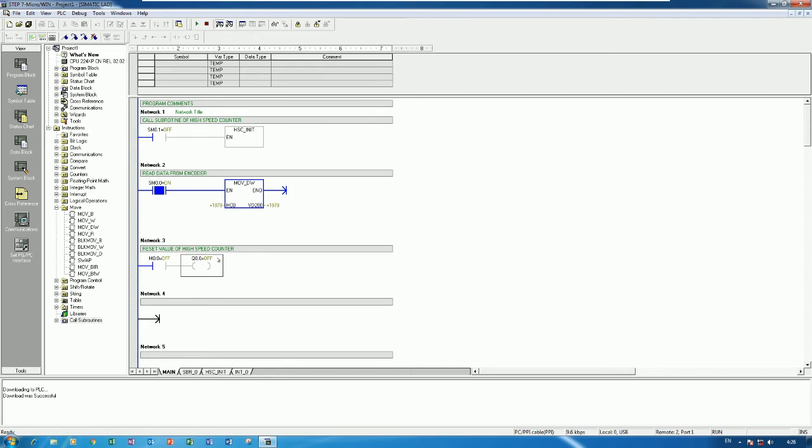And if we would like to reset, we just write this one to on. Actually we can reset from the HMI, right? I will show how to reset from HMI. So here you see the input is turned on, and then the counter is reset to 0, right? Because I already connected the cable from Q 0.0 to I 0.2. Okay, I start to increase and decrease again.